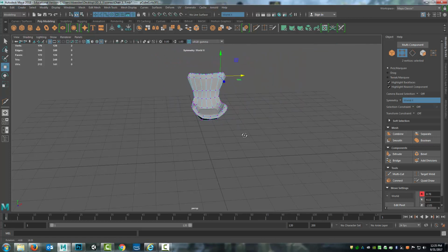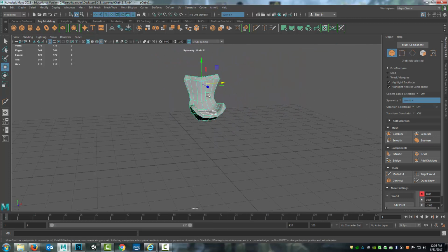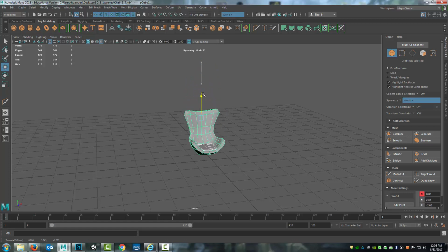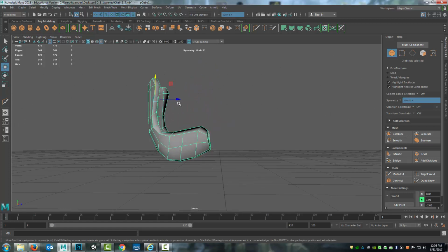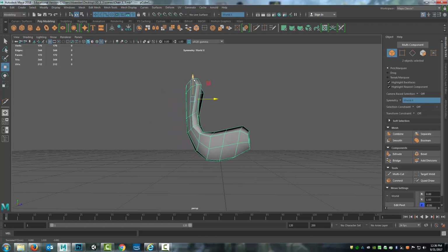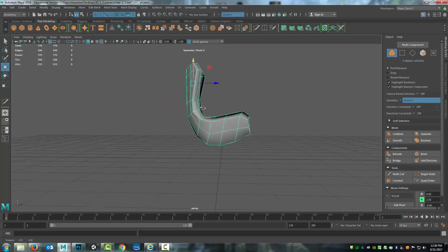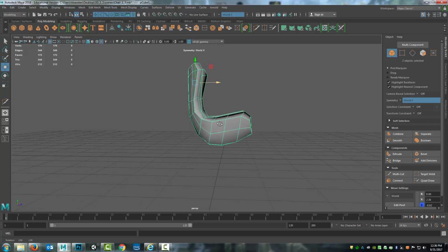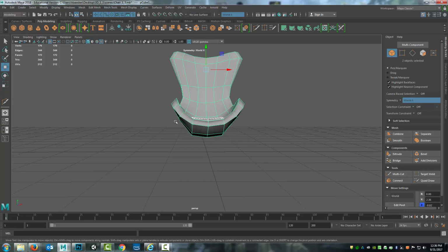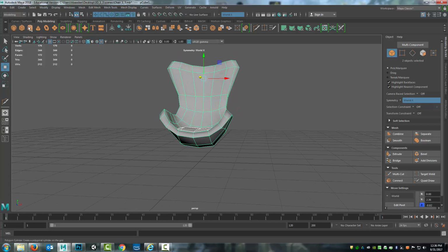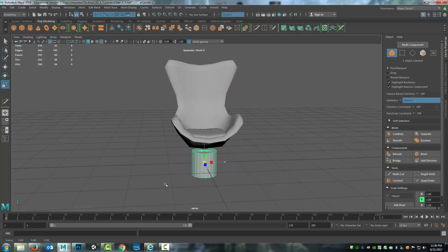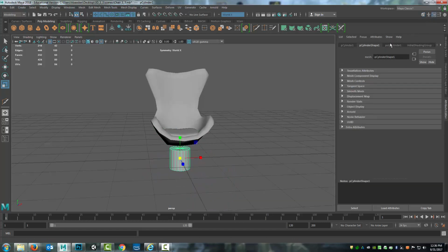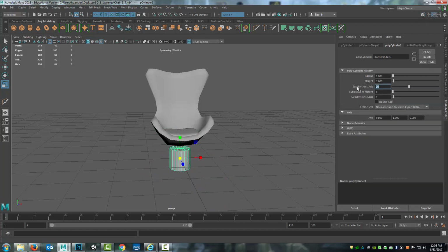And so that'll help me get some of the shaping that I want, but by keeping it simple. Now the chair is already too high, so I'm going to bring these objects down to about where they should be here. That's not very good either. So I'm actually going to bring this forward, make sure it's over that origin. And I'm going to build this cylindrical shape at the origin. Alright, so I will create a cylinder, and I will reduce this down. I'm also going to open up the attribute editor and make sure I change that subdivision to 8.